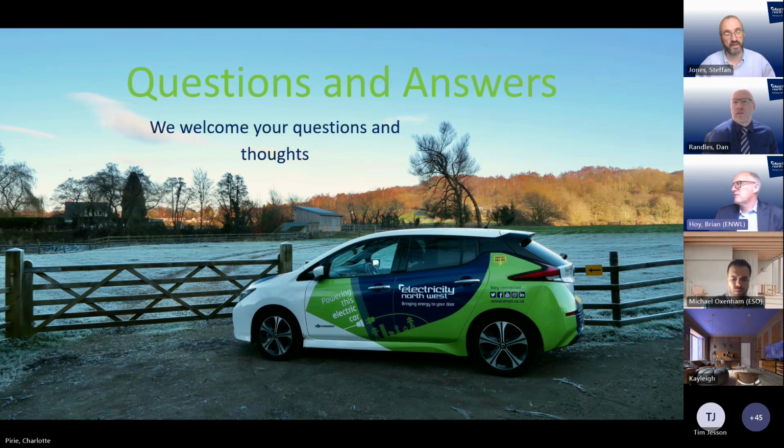Okay, thank you. The last question in the chat is, how is it decided who will be curtailed? I think we haven't made a final decision on this, but Dan, do you want to share some thoughts on that? So we're currently working on how best to implement this. Within existing principles like last in, first off, available within Electricity Northwest, we have something called the curtailment index, which we've developed alongside our A&M offering, which looks to provide a fairer sharing of the curtailment burden.